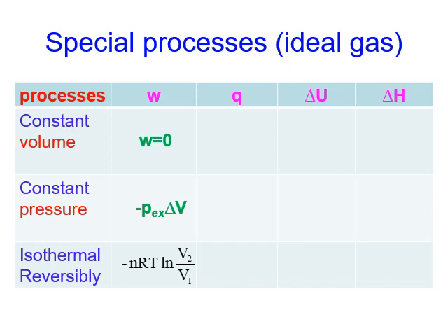How do we calculate the heat? Heat is calculated by heat capacity. For constant volume, we have Cv delta T. For constant pressure, we have Cp delta T. More commonly, we use nCvm delta T, and here nCpm delta T. What if we don't have Cpm?